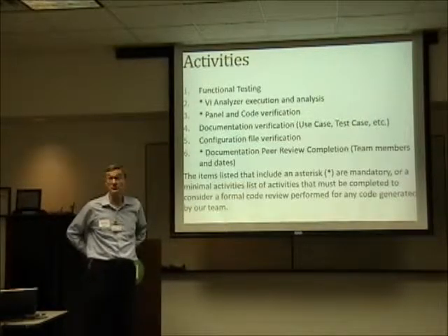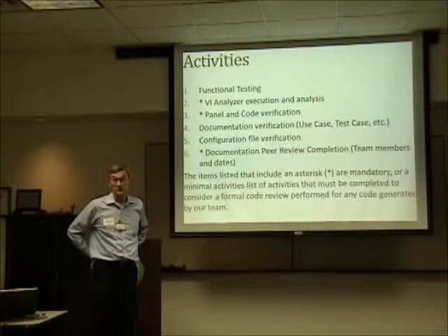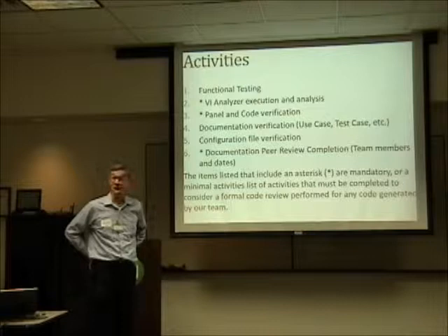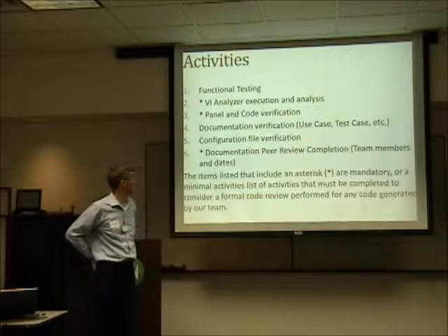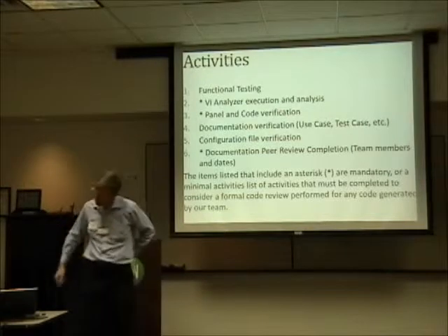Configuration file verifications. We generally use INI files, but I know some folks here probably are using XML or relational databases. What I'm talking about is key equal value. Any tester we have has to have some kind of volts per volt factors or other things like that, setup values if it's a digitizer, those kind of things all end up in a key file somewhere. So checking those out. And then finally documenting that the peer review is complete.